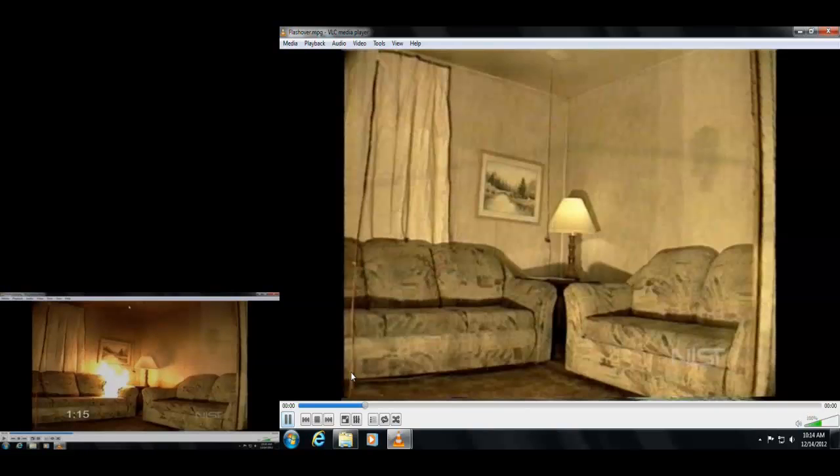Now, at this point, I think this is an important issue to think about. We can still see the ceiling. We can still see the details of the wall-ceiling interface. And radiatively, the fact that we can see it means that it can see us. So although the smoke is starting to obstruct this view somewhat, for the most part, even in the visible, we're able to see through this smoke and see the ceiling.